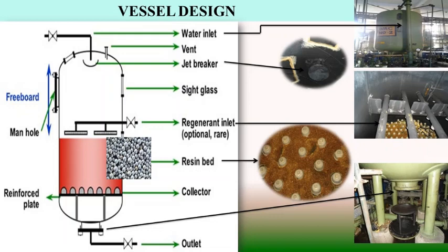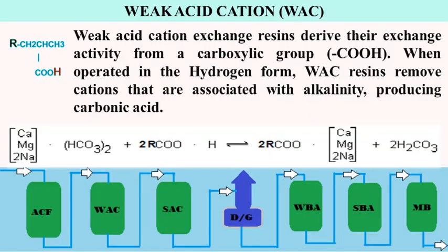Vessel design: we find that they are designed as a closed vessel with water inlet and outlet arrangement, and this vessel is provided with a vent and side glass to observe the resin status. Regenerant inlet arrangement and collector plates are also present to arrest resin slippage.